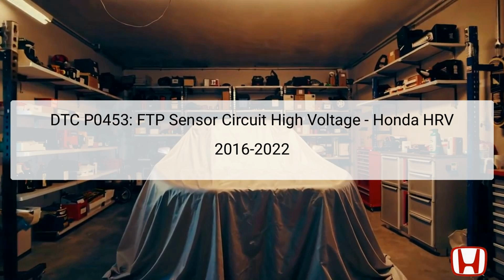The FTP sensor is typically located on the fuel tank and is connected to the vehicle's powertrain control module, PCM. If the sensor detects a voltage higher than the acceptable range, it triggers the DTC P0453. Understanding this code is vital for diagnosing evaporative emission control system malfunctions effectively.